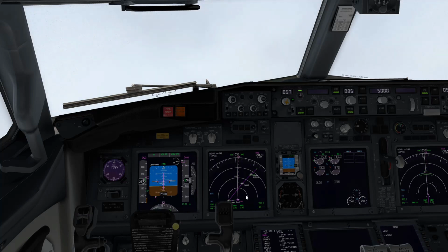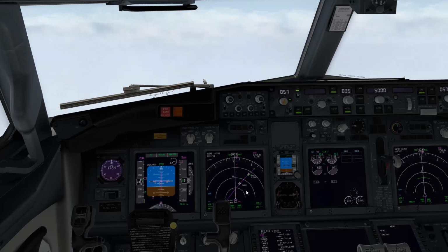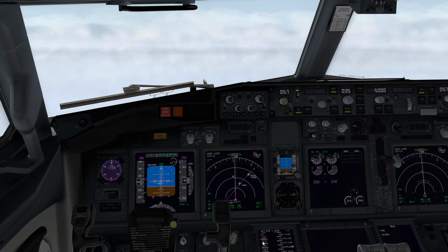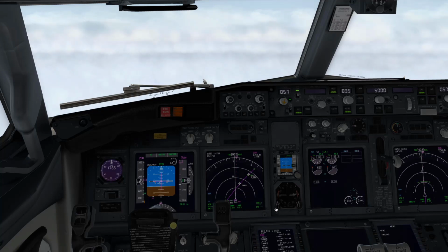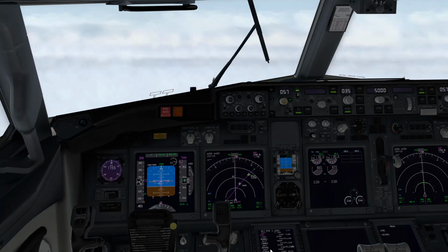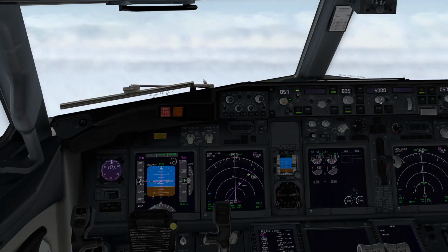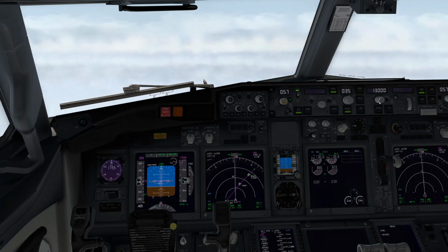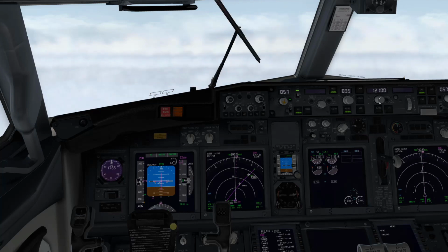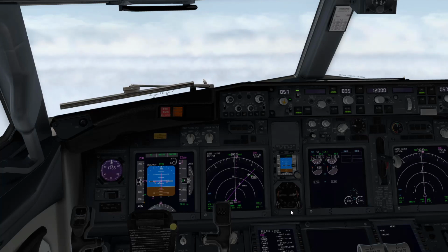Oh, I see. It looks like our track was taking us off to the left here. I should have flown that heading on departure, but it seemed to have sequenced in some way, so accelerating now to 250 knots. Let's just assume ATC says, okay, now you're clear to 12,000 feet and fly direct to Tango.